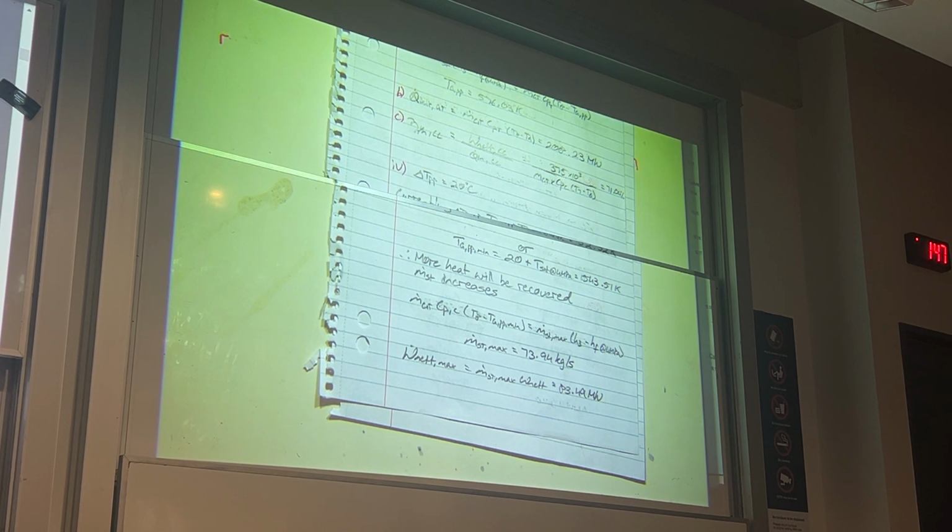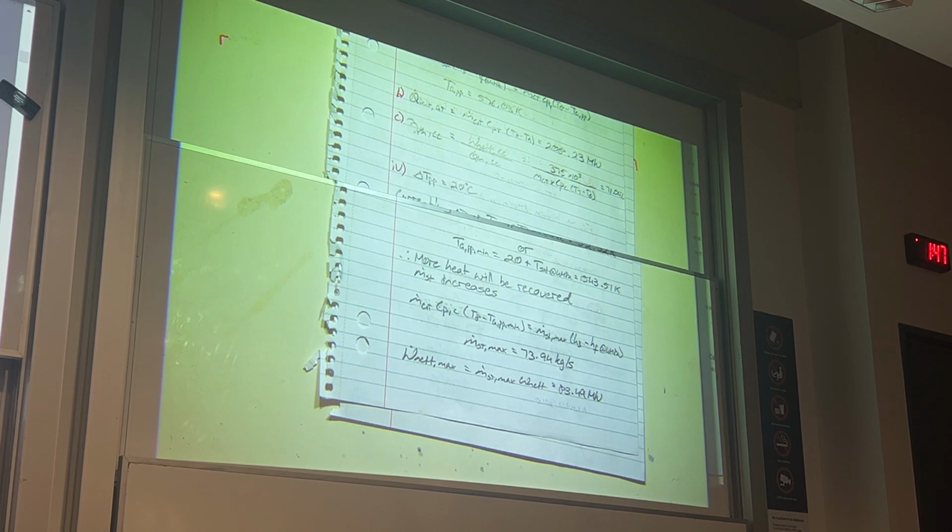Oh yeah, that just relates back to remembering our pinch point occurs when our water begins to boil. So we have to do the energy balance from here to here. So if we can't use T9 and T2, we have to use this temperature here, and then the trick was you should see it's flat, so we know it's beginning to boil. So it must be saturated, because it's on the steam pressure.